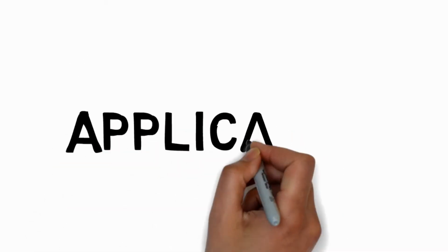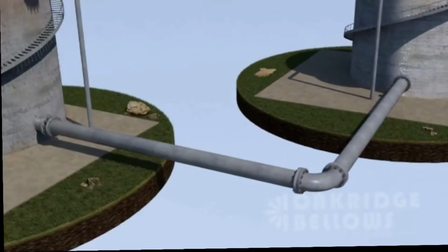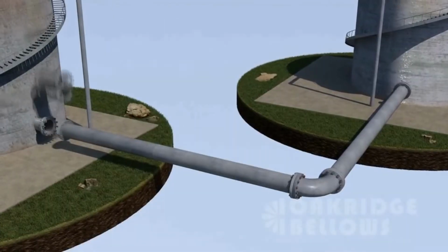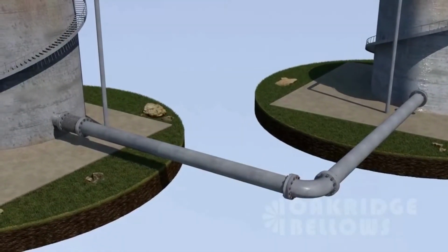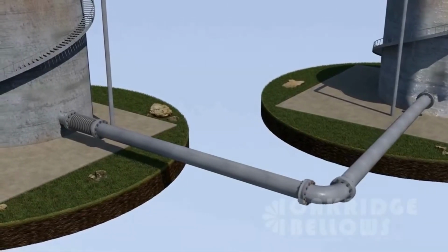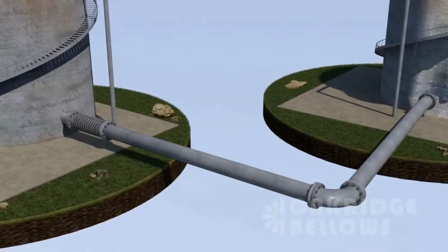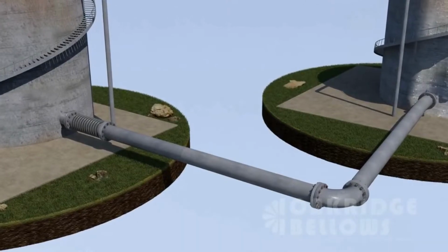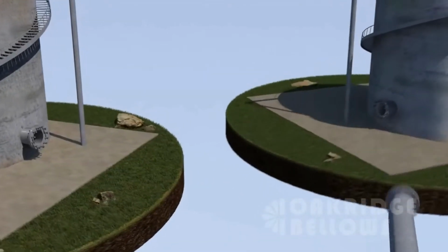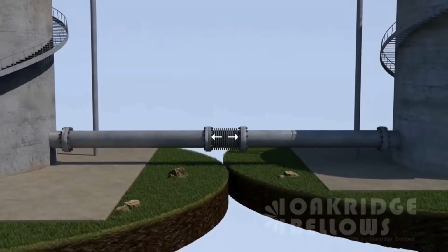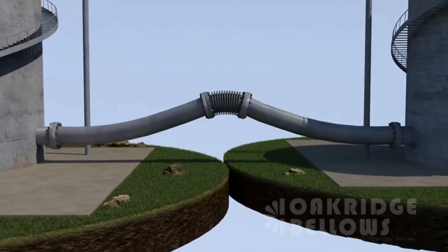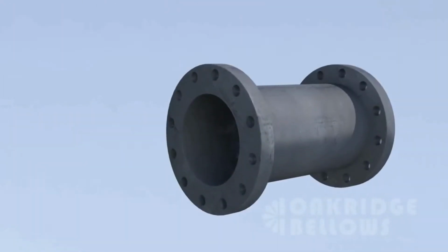Moving on to the application of a bellow. An example is a system that's not properly anchored and guided. When you introduce some flexible metal bellows and pressurize the system, it is going to push over the piping. That's because of a pressure thrust load, and another is a straight piece of piping, same thing, that load is going to buckle the piping and it's going to kick out of place.